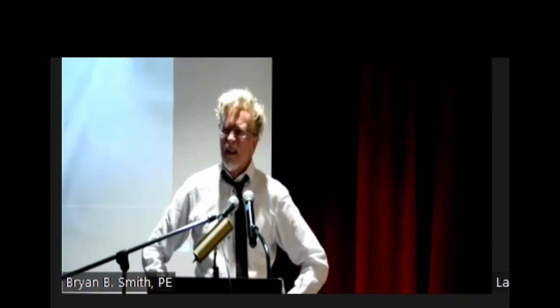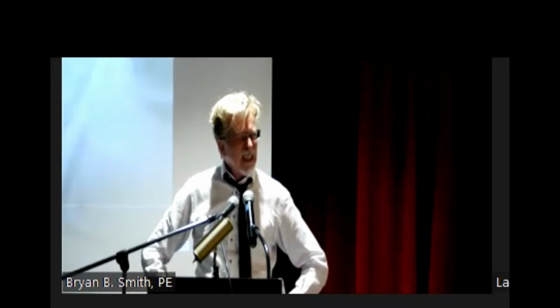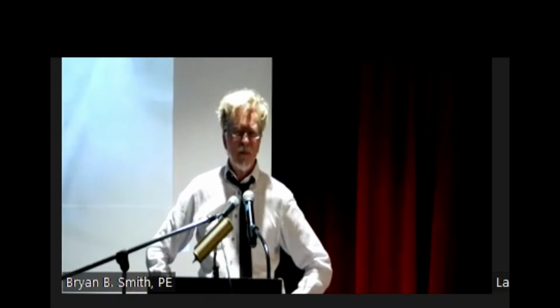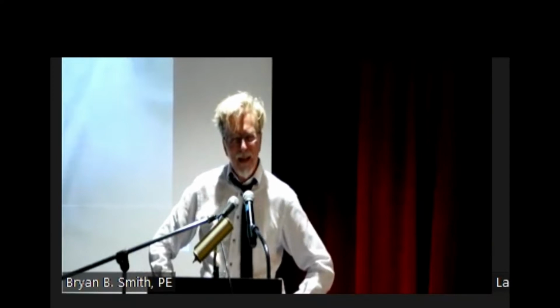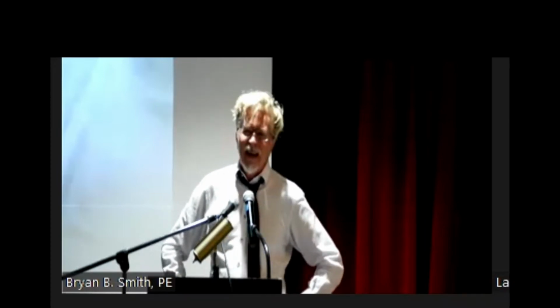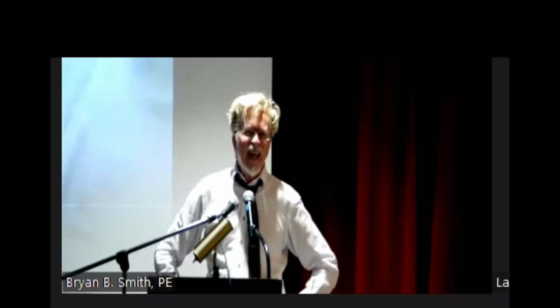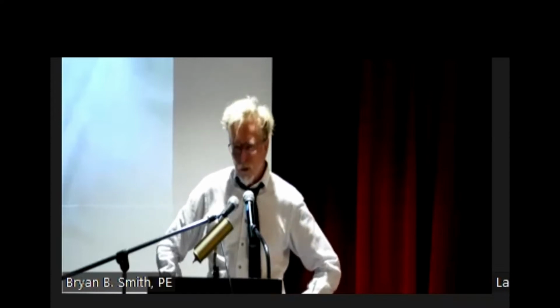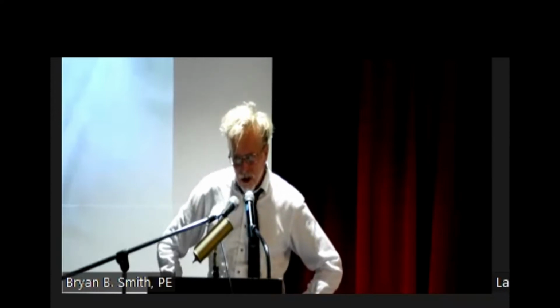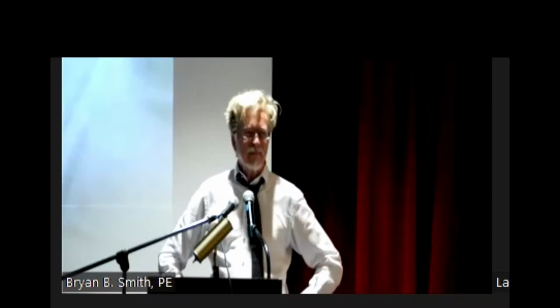So this was a flaw in the software going back in 2006, designed a beautiful pump station, force main. It's like, oh, this is good. I love this one, right? And it's like started up and the pipe goes, I'm like, open up, air vacuum valve. Come on, open up, right? Well, the software said the vacuum valve is going to open up instantly. Okay, it didn't open instantly.